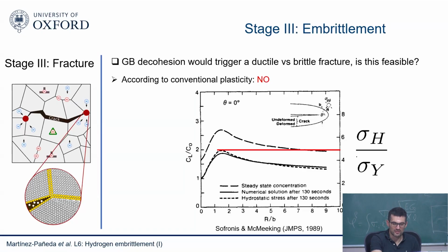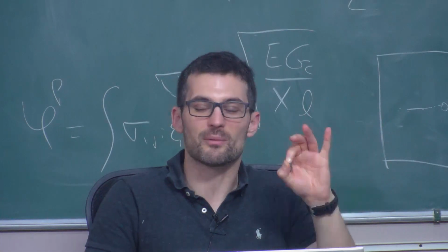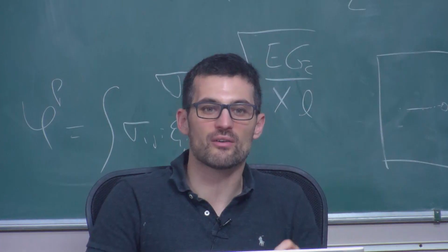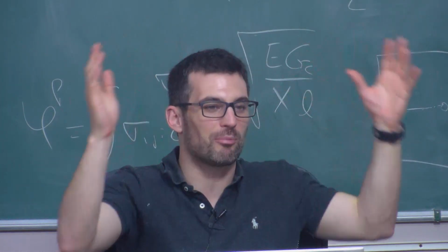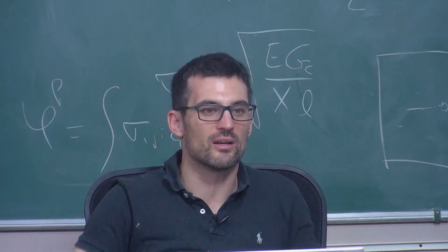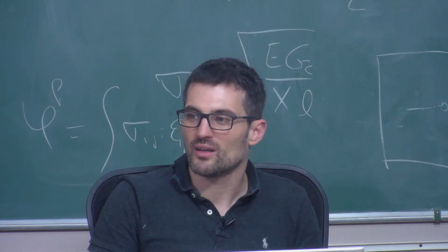That's something I'll discuss tomorrow because we only have 7 minutes left, so it's not worth opening a set of slides again. But it's a problem that relates not only to hydrogen but also to many other mechanisms, quasi-cleavage and low temperatures. Anytime you look at an interface that has broken, you say, how can this possibly be? That interface has a very high strength, and our stresses are not high enough. We also see in metal-ceramic interfaces plenty of plasticity, but still very sharp cleavage-type failures. So there's some discussion related to that.